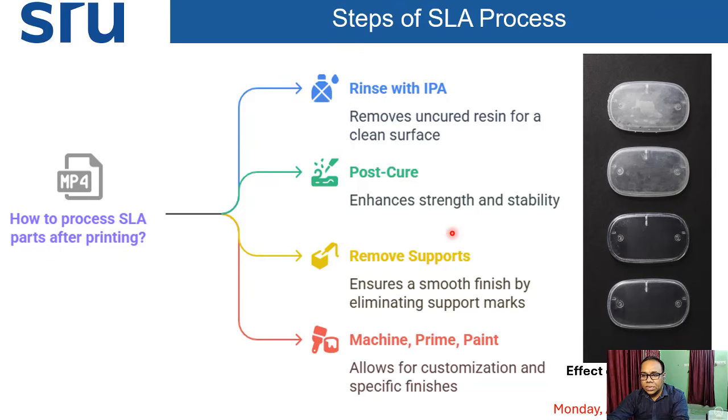So these steps are required for curing, or getting better surface quality of the 3D printed or SLA printed part. You can see from these photos that the first part is dull in color. Similarly, the next one is less dull, has some better clarity, and the last has a totally clear picture of the printed part. So by doing the post process only, this is possible.